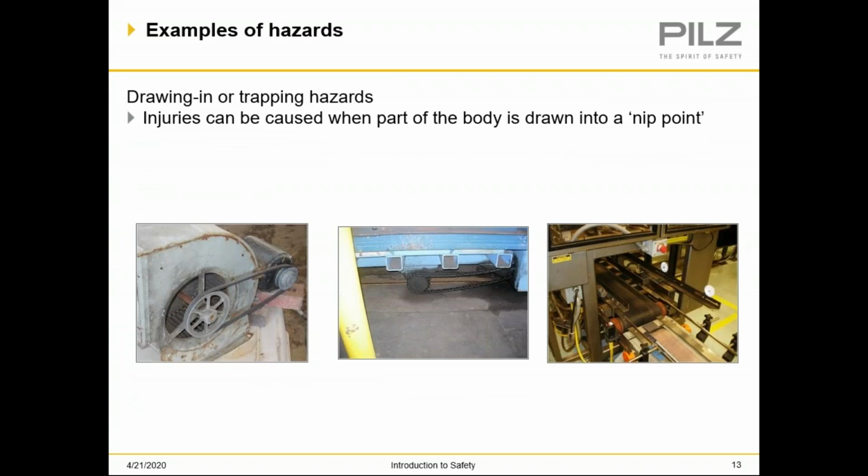We see these a lot with the pulley open, no guard over it. There in the middle, the sprocket and the chain, a real good place to lose a finger or a toe, depending on how hard that's driven and how big that is. Also conveyor belts, drawing in. I don't know which way that one's running, but it could definitely have a pinch point involved.